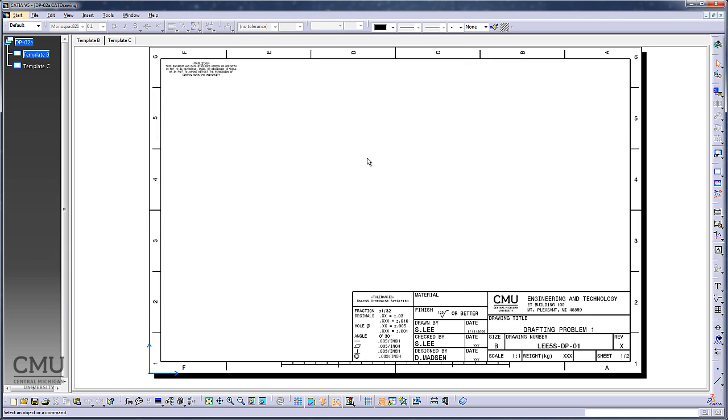So the first is the front view, then the right side view, then also I'm going to have an isometric view with a scale as well. If you look at the book, for the dimensions shown, we have a front side. As an example, 1.255, 45 degree, datum M, and a couple of feature control frames showing in the front.